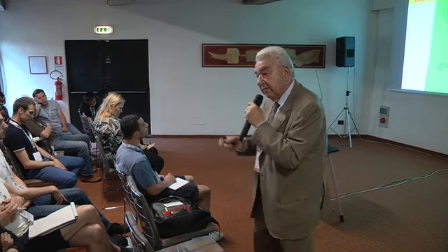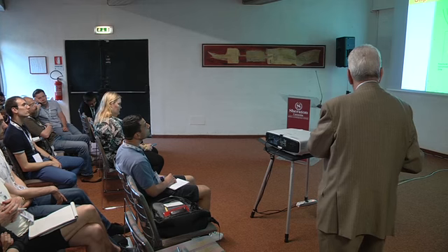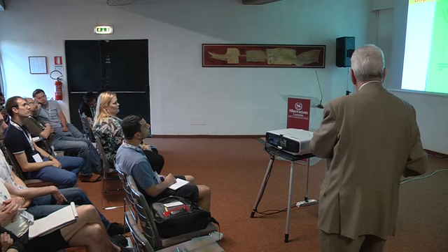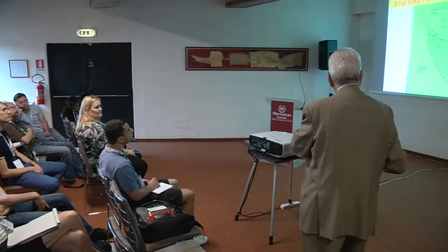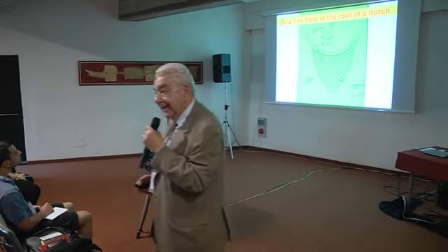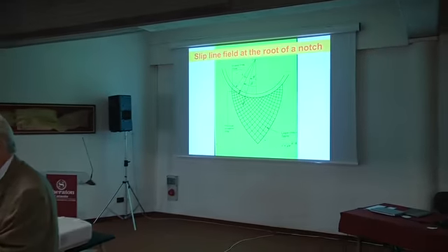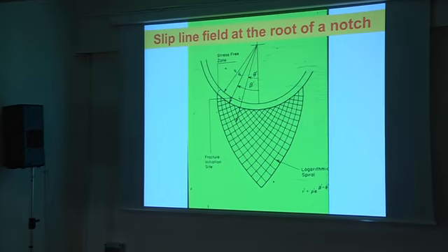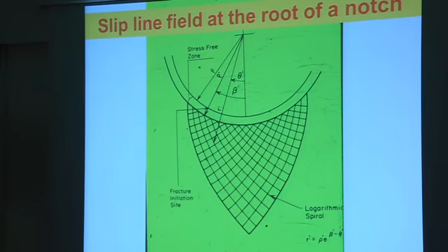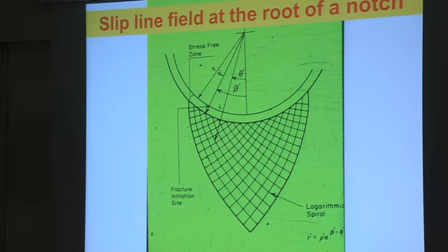So you can have a fracture along this line, which is a logarithmic spiral, or the corresponding one on the other side. And in the same specimen, you may have fracture that begins on one side or on the other. You may have fracture along one of these lines and fracture along the intersecting line of the opposite fan, and again going back. And in fact, this is what we see.